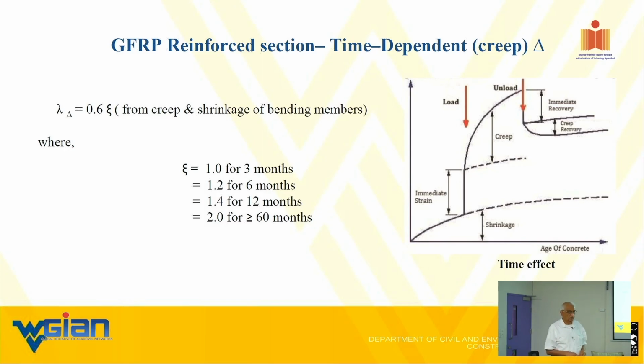I don't know how many of you are aware that the modulus E value is a time dependent function. So if I have applied the load suddenly, I have a modulus higher than the static one. If I applied load gradually, I have a modulus that is lower than that. There is something in between.